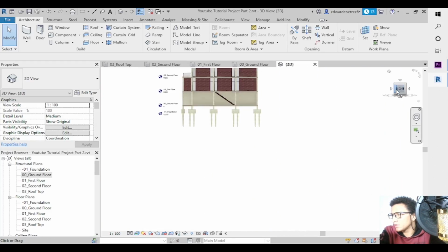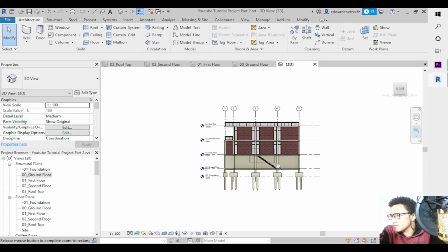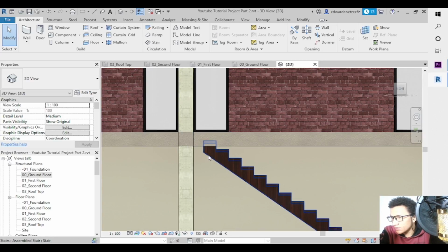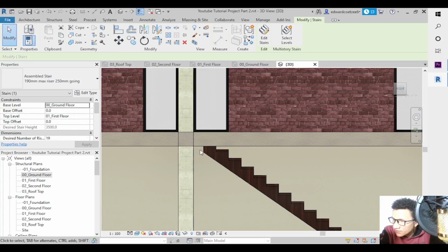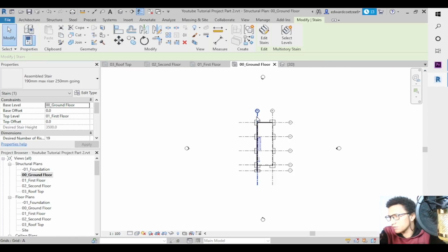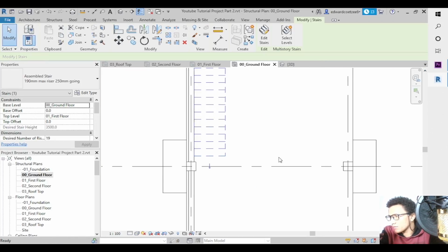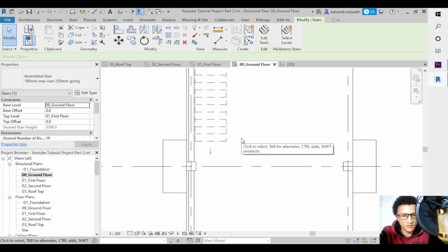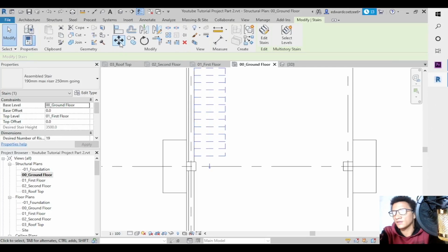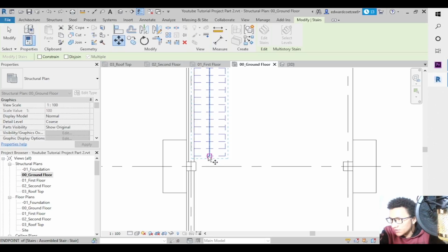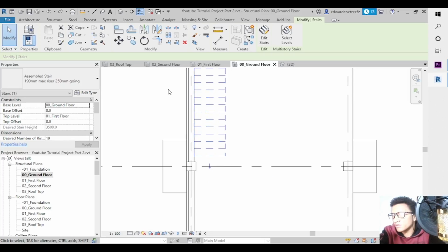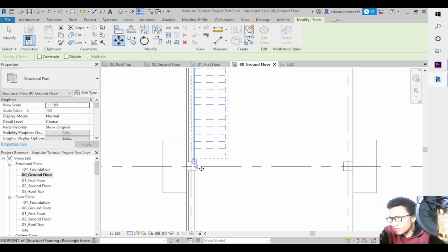So what you can see here from the side, just move to the top. Here you want that section to be onto your beam so that there's a resisting support. You go to ground floor, you zoom in, you say undo, Control Z, you move it from that point, because your beam is also running somewhere there, flat in line with your column.